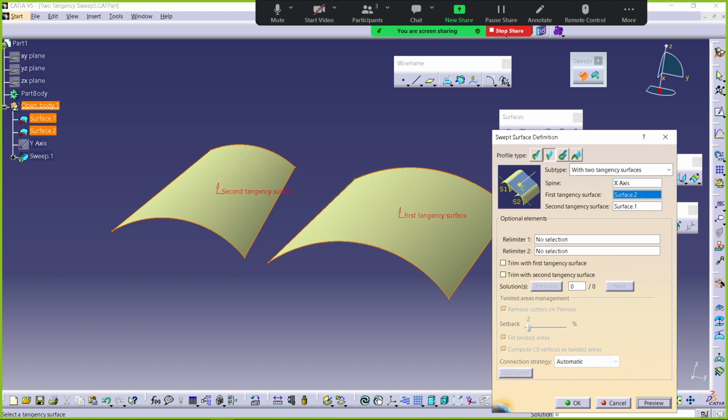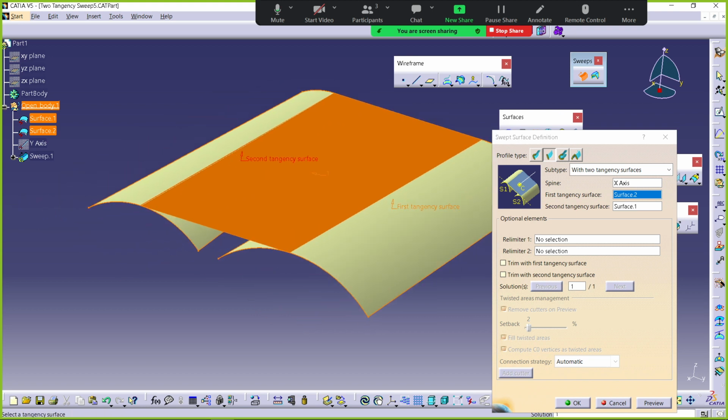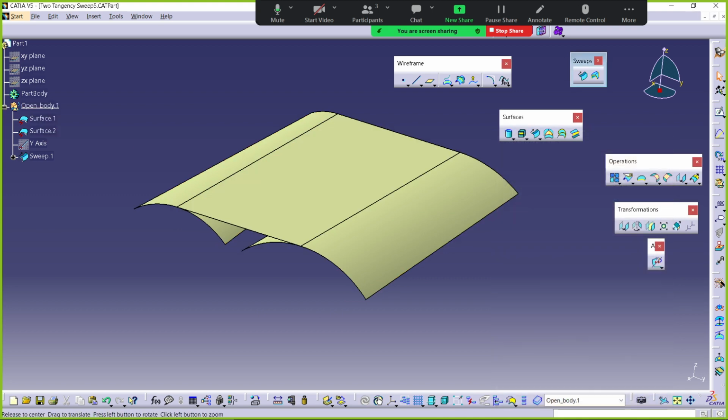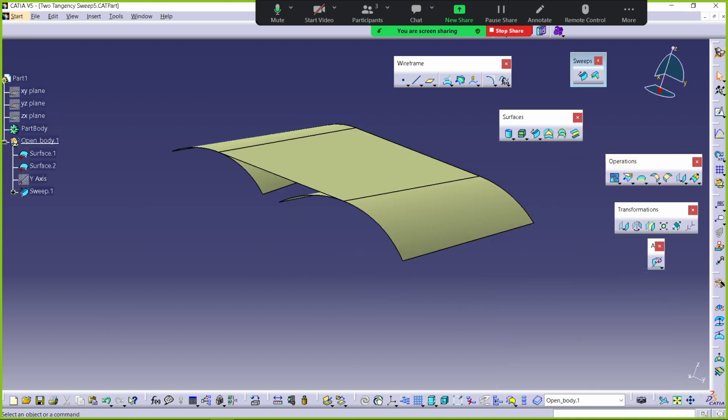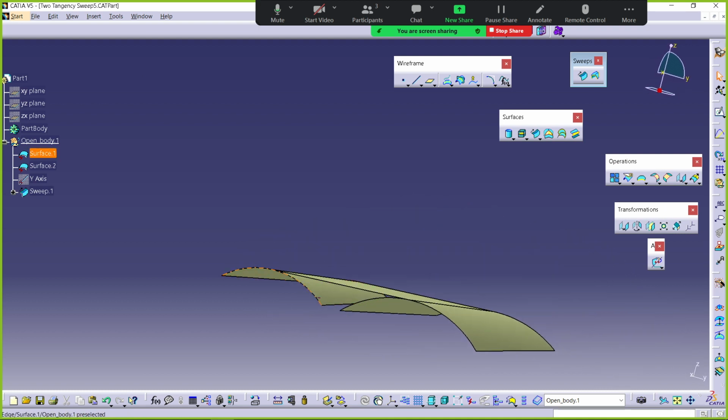The surface is generated with respect to the x axis, and the first tangency surface is this one, the second tangency surface is this one. You can see while creating, it is connected to these two tangency surfaces. But you don't want to generate this one, you want to remove this one. For that, what you need to do in this sweep...